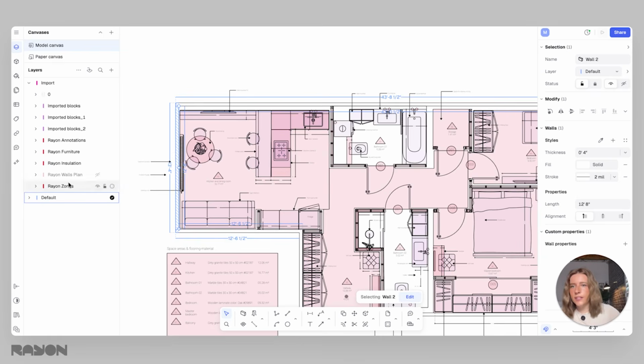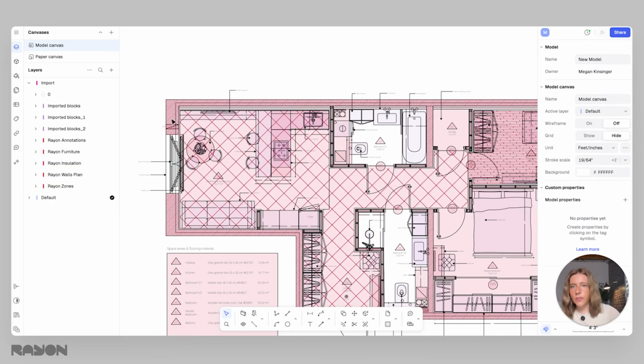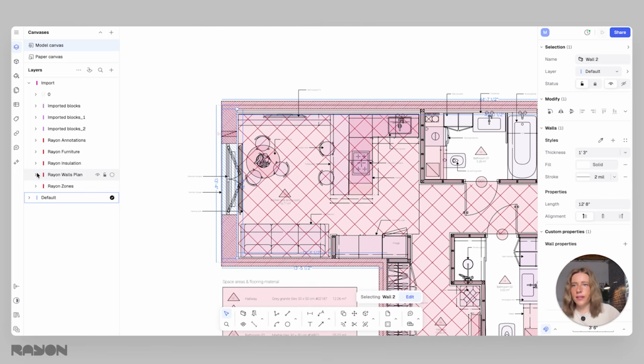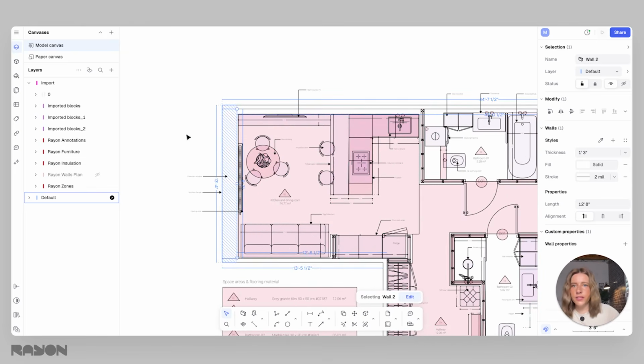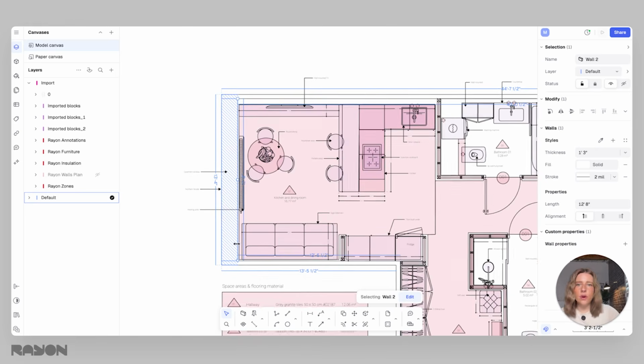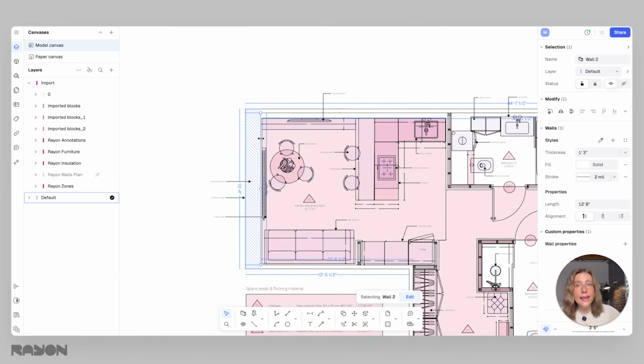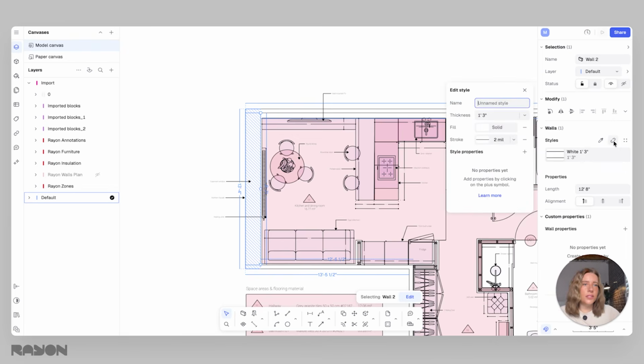I can easily extend different areas. If we need to change the size, we can just create a new style. So for instance, this outer wall was a little bit thicker. So maybe that wall is 15 inches. And again, I'm gonna turn off the walls here so we can see that. And now you can see that that wall is thicker. And if I like that style and I wanna save that style and use it again, then I can just hit this little plus button and say save style, and this will be like thick exterior wall, or you know, something more sophisticated than that.